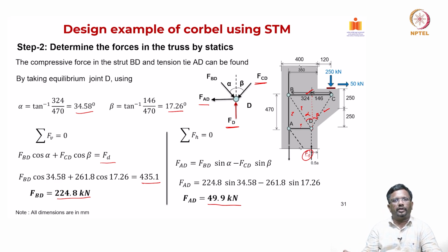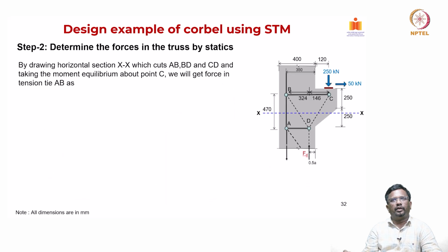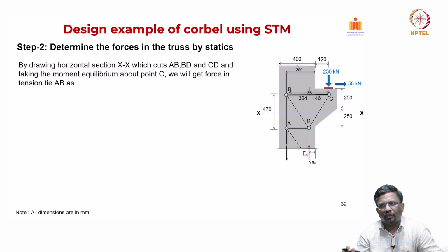So now we have found out this, also we have found out all the forces that we wanted, right. So we can go back and okay. There's one more thing that we have to find out. We have to now find the members. We can cleverly do it by using the method of section. You must have studied in your basic engineering mechanics course. You can take a cut which is cutting through the members to expose your internal forces. Then you can use your statics to find out the unknown forces, right.